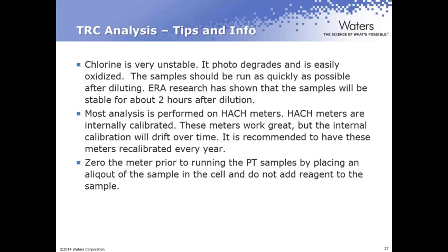However, certain factors in your lab will cause that calibration to drift over time. As with most light bulbs in your house, the bulb doesn't just go out. The filament doesn't just blow. The bulb weakens over time, so that a 1 part per million standard today might give you 10,000 counts of light, whereas 6 months from now it may only give you 9,000 counts. So that intensity of the bulb will diminish over time before the filament on the bulb does go.